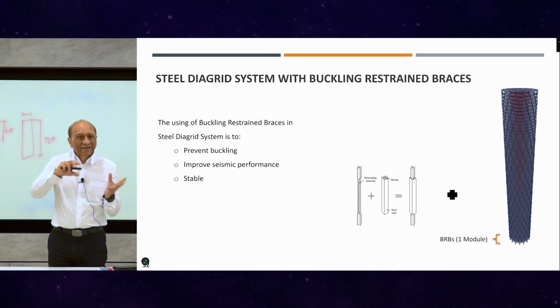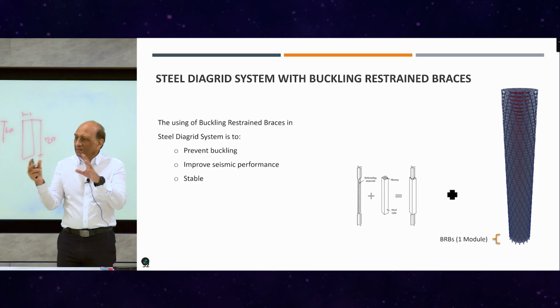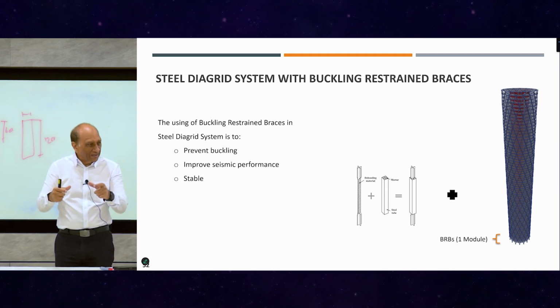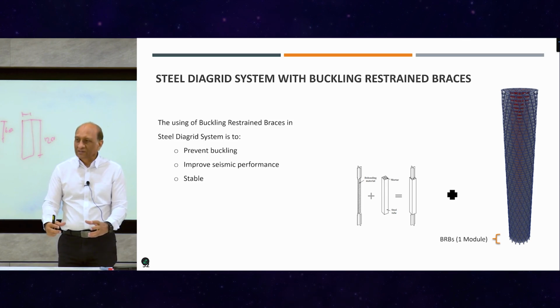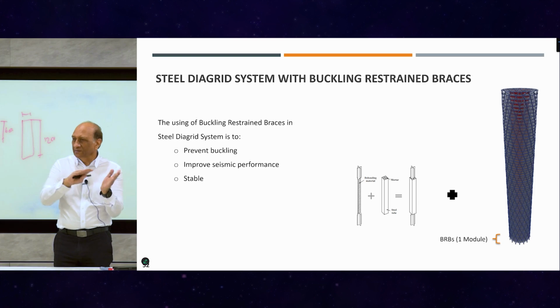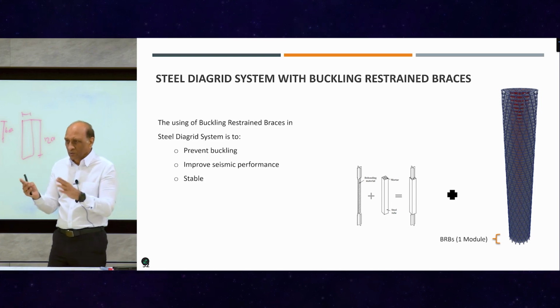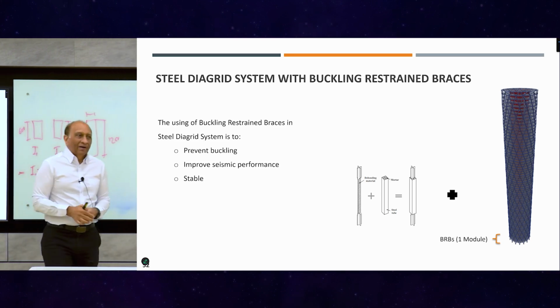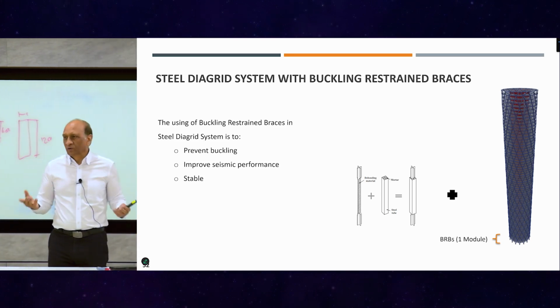So they become like a hinge for the whole building to dissipate energy. So the rest of the building becomes elastic and stiff with a hinge at the base, which allows it to rotate and yield during high seismic zone and reduce the forces, of course, because it will yield. But at the same time, it's a BRB, so it won't fail.